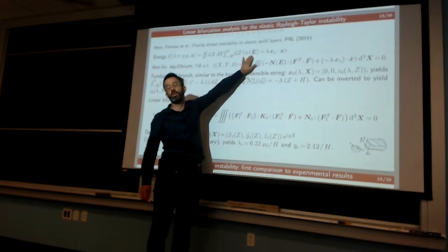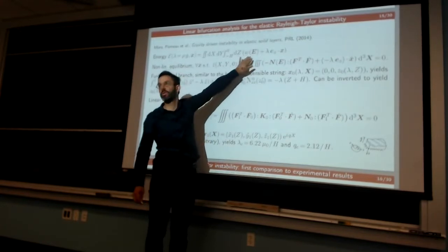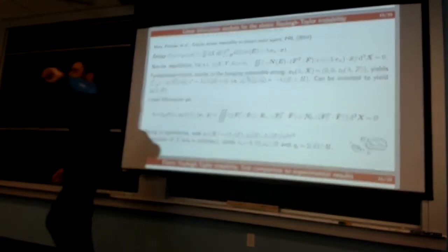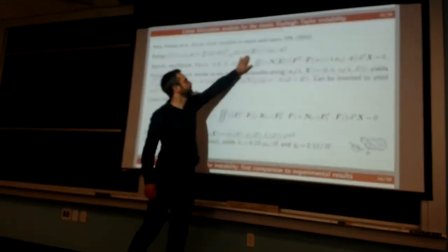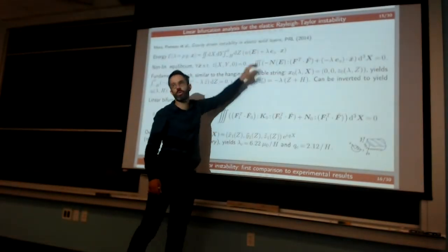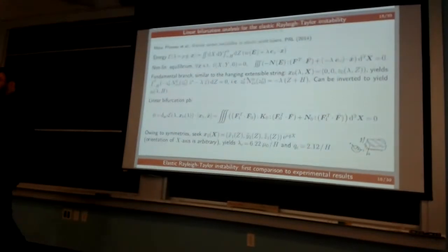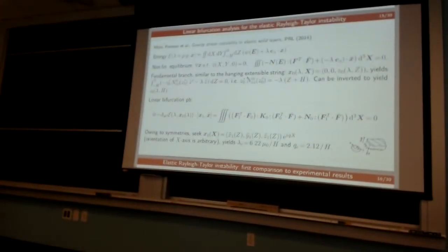In the real work we use an incompressible material, but incompressibility complicates the formulation a little bit because we need to impose extra constraints. So let's forget about incompressibility and just take some material coefficients such that the bulk modulus will be much larger than the shear modulus.